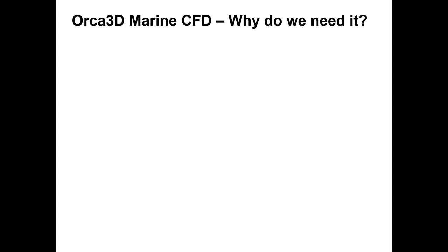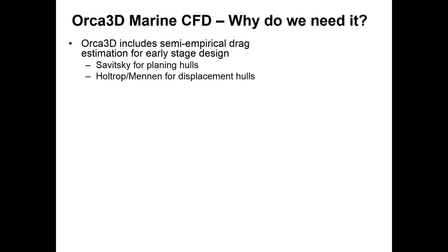So why does someone designing a new boat or modifying an existing boat need CFD in the first place? Well, for many years we've been predicting hydrodynamic performance of our designs using a combination of our own experience, rules of thumb, and empirical prediction methodologies. In fact, Orca3D includes two semi-empirical drag estimation methods, one for planing hulls using the well-known Savitsky approach, and another one for displacement hulls using the Holtrop and Menon regression-based approach.